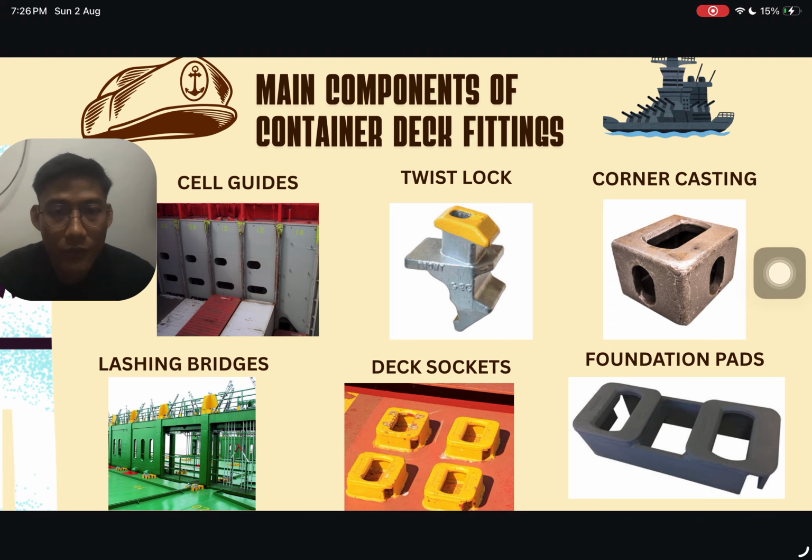So lastly, we have foundation pads. These are strong steel plates fitted on the deck to support securing equipment and distribute the load more effectively. So all these components work together as one complete container securing system. Their purpose is to keep containers stable, protect the cargo, and ensure safe operation throughout the voyage. Thank you.